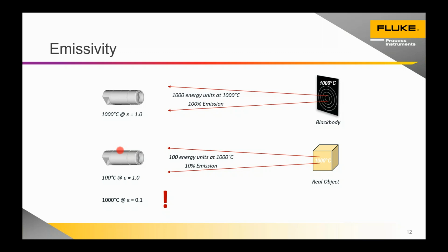On that particular device, the wavelength is optimized to give us the best path through atmosphere at different humidities, so we get no effect. In general purpose low temperature sensors, we're also only touching CO2 at the very long wave. So generally no effect. Day to day with the average sensor, it's not something that we need to consider.